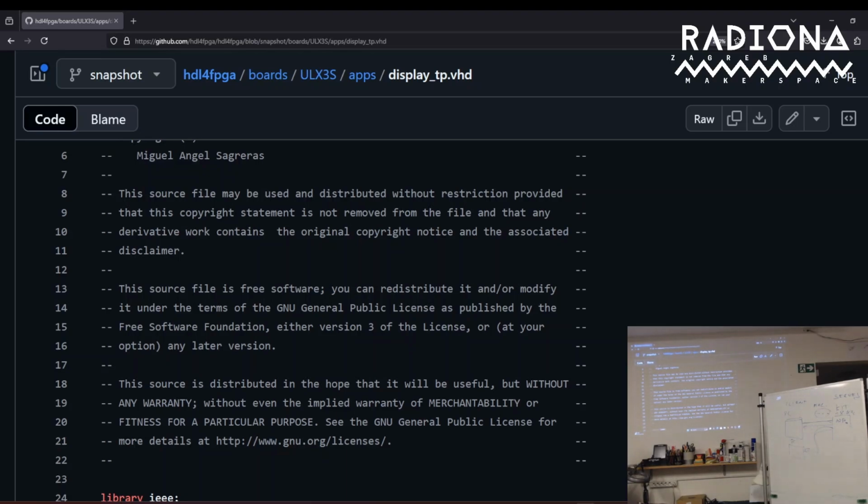Again, with the Ethernet, similar to DDR3, the question is about the PHYs, but the PHY with DDR3 is inside the FPGA. No, this is a completely separate module. You can use it or not, you are not forced. You need an external PHY, or you don't. You just toggle wires directly from the FPGA with this. Oh, this is hardcore.